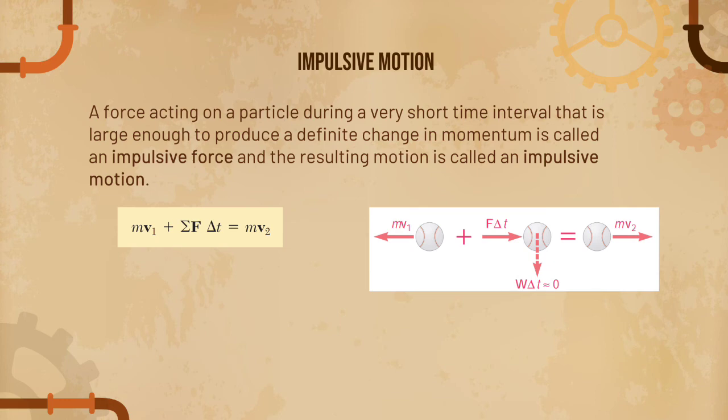Unknown reactions may or may not be impulsive. Their impulses should therefore be included as long as they have not been proved negligible. The impulse of the weight of a baseball considered above, for example, may be neglected. If the motion of the bat is analyzed, the impulse of the weight of the bat can also be neglected. The impulses of the reactions of the player's hand on the bat should be included. These impulses will not be negligible if the ball is incorrectly hit.